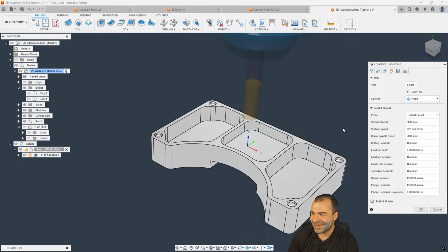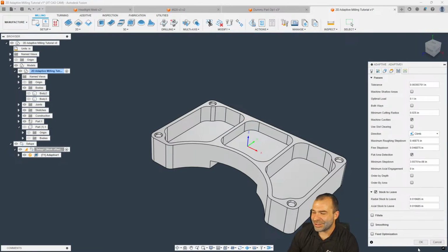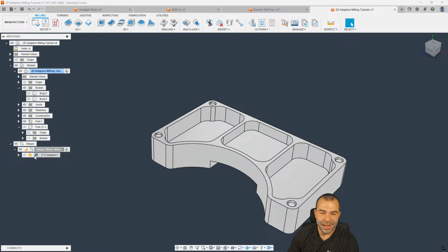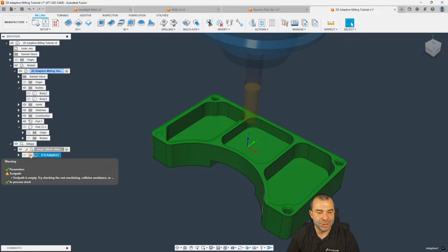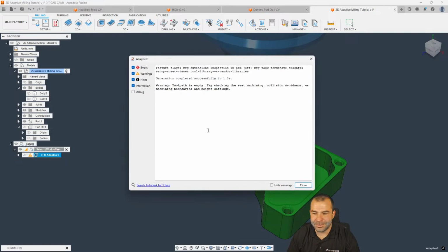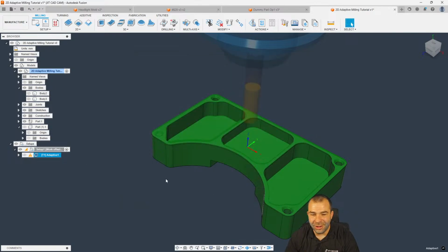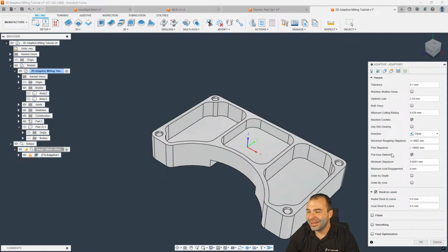And now let's go back to that tool. So initially, I just got an error. And the reason why I got that error, if I can back it up here real quick, is because there's nowhere for that tool to actually machine, right? So it says Toolpath is empty. Well, can anybody in chat go ahead and guess real quick why it says Toolpath is empty? Deep thinker, I'll jump back to that here in a second. But the reason why I have an empty toolpath is because my stock to leave is basically identical to what else I had going on.